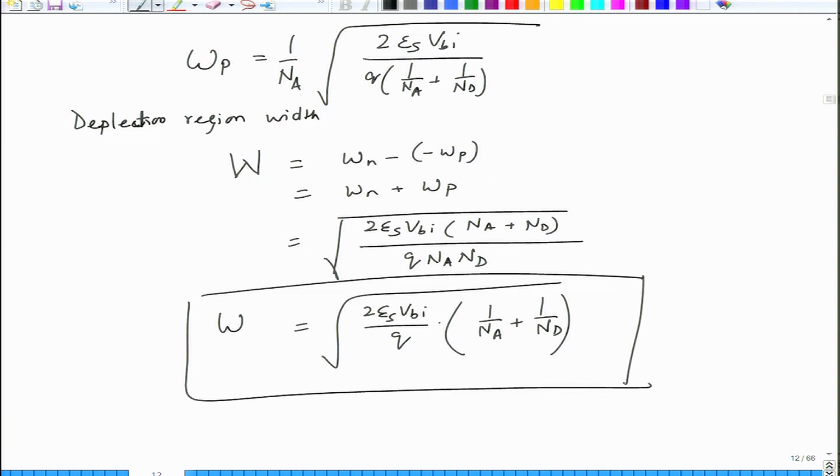This is the relation of charge density, or you can say acceptor and donor density, and the built in electric field with respect to the depletion region width. So, what it tells you is that when the donor and acceptor density increase, the W goes down. So, this is what we have done in this lecture. We have looked at some electrical parameters, the continuity of potential, electric field, the basic equations for electric field and potential.